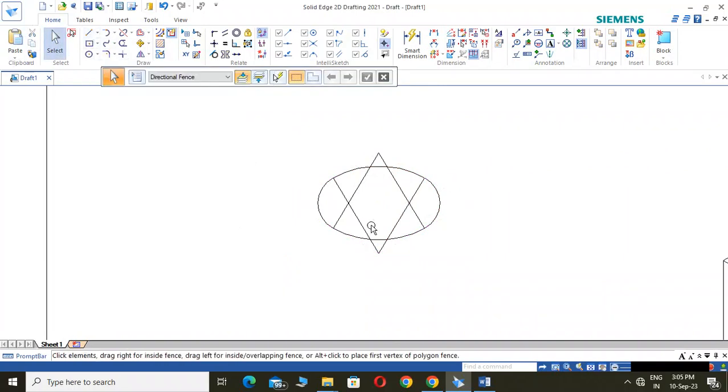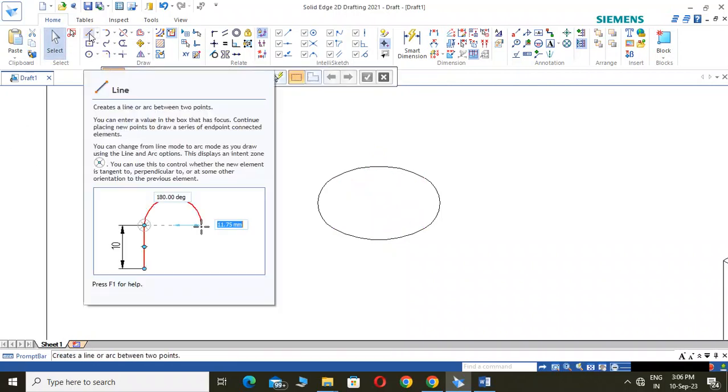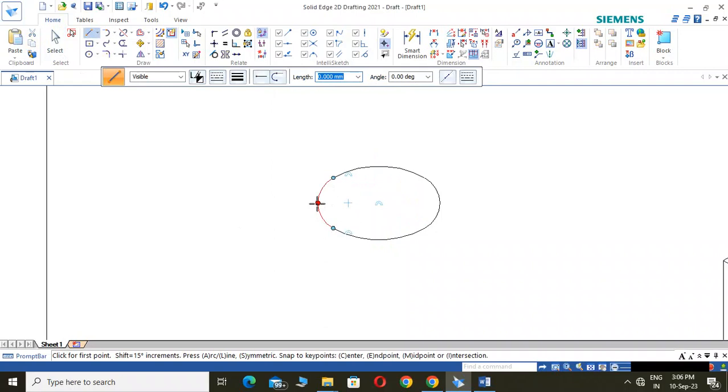So, this is a midline. Even this construction, by pressing Ctrl, you can select all the lines. You can delete. Now to draw the height, we need to have a midpoint. So this is the line from here. I will draw one line here to identify the midpoint.